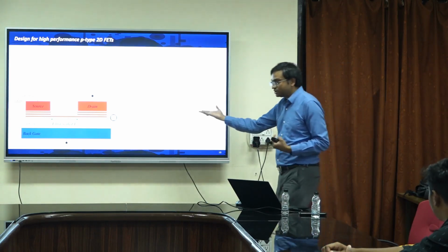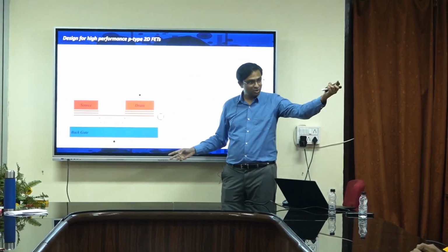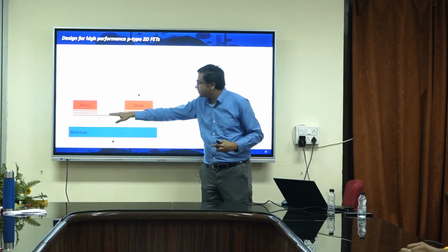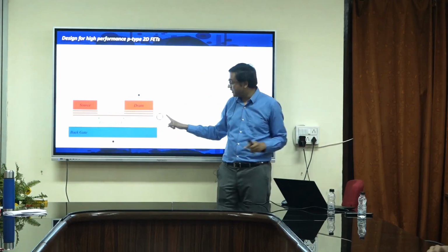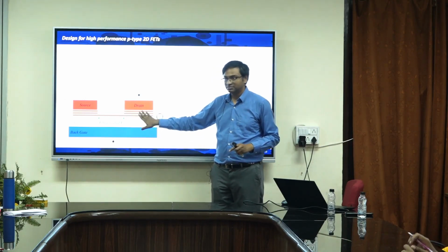So I know that I don't need to keep my entire channel thick, because then I will lose the gate control. So I need to make sure my channel is thin so that I have the gate control, while my contact resistance has to be reduced, so this has to be thick, right?